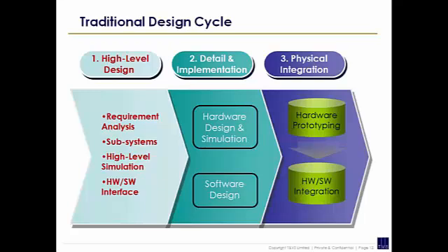Software development and debug performed on frozen RTL, or almost frozen RTL. That's why I put almost there, rather than on the first silicon. Efficient reduction in time to market and delay of the product, scope to fix system level bugs in hardware rather than a software patch. I spoke about it. Risk spins efficiently avoided. System performance measured at a very early design stage. Okay, this is also important. System performance is measured at an early design stage because of co-verification.